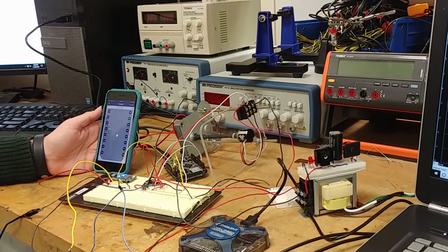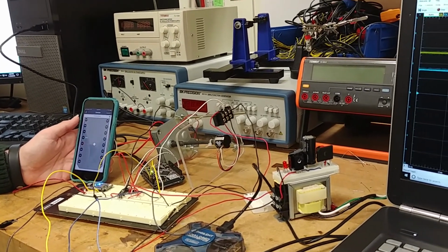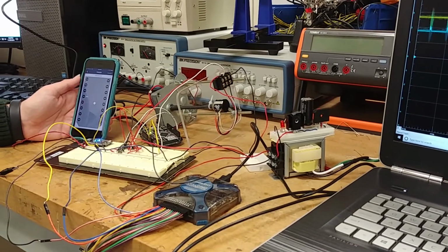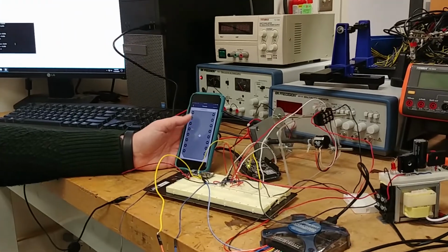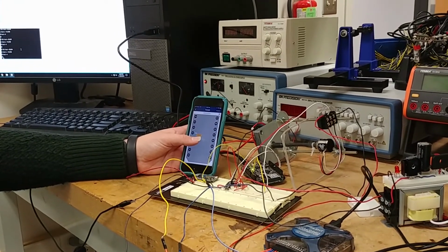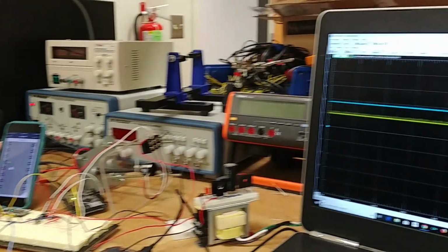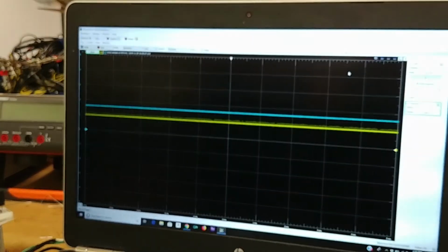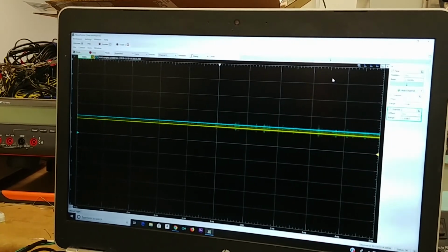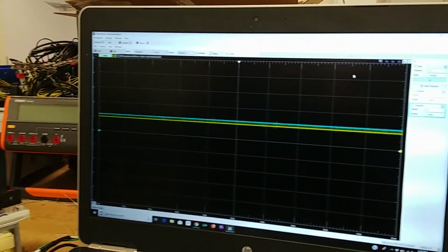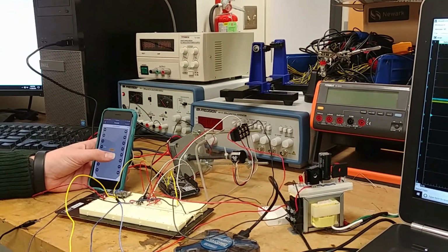Then we connected it to the mbed, H-bridge, and a small DC motor to confirm that it would function as desired when we changed the set point on the phone. Throughout this process, we used the Analog Discovery kit as our oscilloscope whenever we wanted to look at the signals, and we also used it as a 3.3 and 5 volt power supply during early testing and setup.